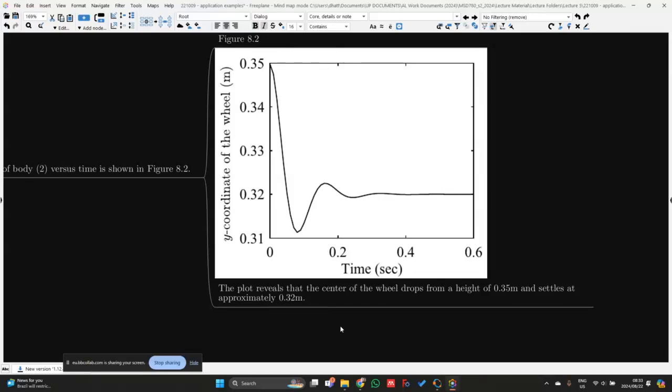Yes. So if you consider your suspension system, so that coil over spring damper system, if it was only a spring and you only had spring stiffness for your wheel as well, you would see more oscillations over here. So you wouldn't have this dissipation after 0.4 seconds. It would be some oscillatory motion that you have. So that includes the stiffness of the tire and spring. Yes. So if you didn't remove the damping on the coil over spring, you would still see some sort of a dissipative force over there.